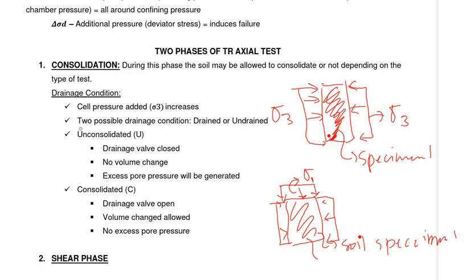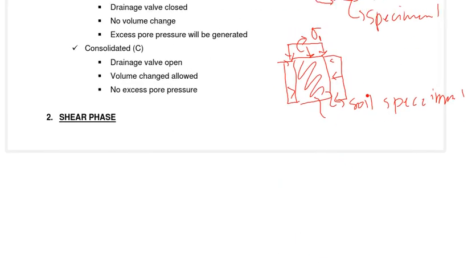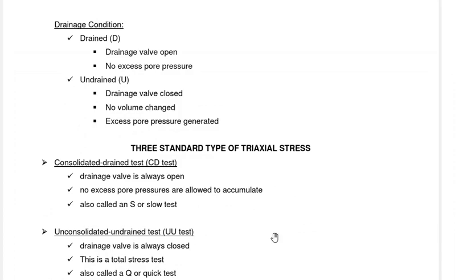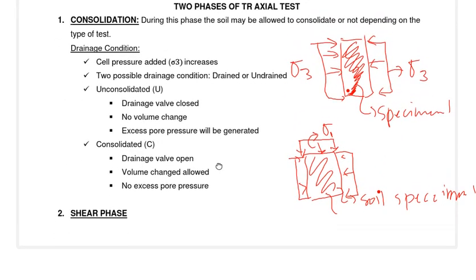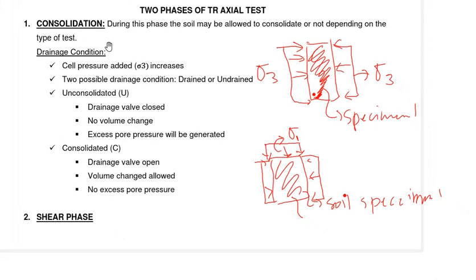Now, going back to the first phase, our consolidation. So in phase 1, consolidation, pressure is added to the water surrounding the specimen, providing a confining and consolidation stress.